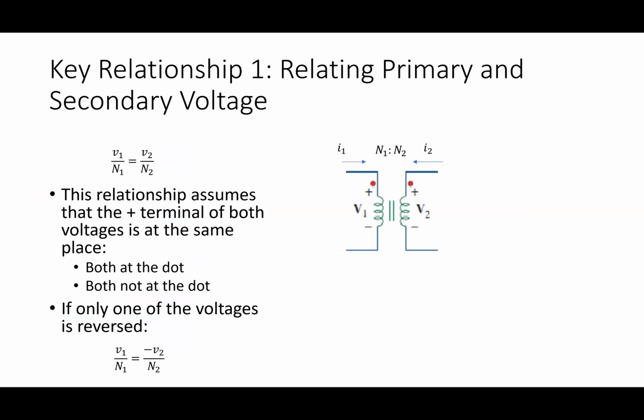Does the power of the second winding depend on the power of the first winding? Yeah, so let me try to walk through that slowly here. The way that I think about this is I try to relate the primary and the secondary voltage like this. The basic relationship I have is V1 over N1 equals V2 over N2. That's our key basic relationship. That's the last time we need to talk about physics. Physics got me to that. The rest of it is going to come from circuits.